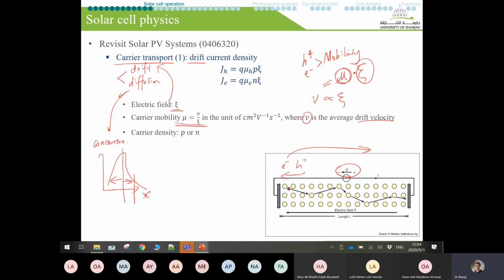So basically, you can see from the current density definition here, we need to distinguish a hole current and an electron current. As we said, mobility times the electric field is the velocity. So essentially, what do we have here? We have the elementary charge q, times n or p, the density of electrons or holes, and then times the velocity, lowercase v. So what does this mean?